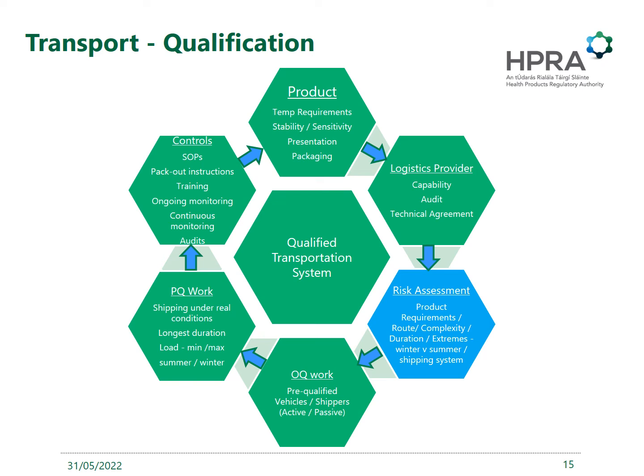Risk assess. You need to carry out a risk assessment on the transportation, not only in relation to product requirements, but also think about the route, the environments the product will be traveling to, the duration of the journeys, the effects of the seasonal extremes on the product, and the different shipping systems that are available.